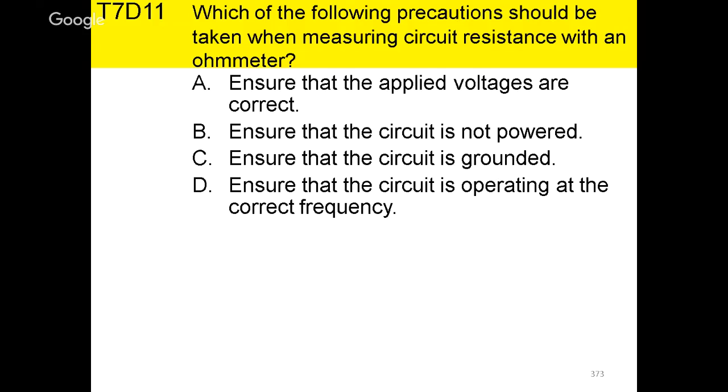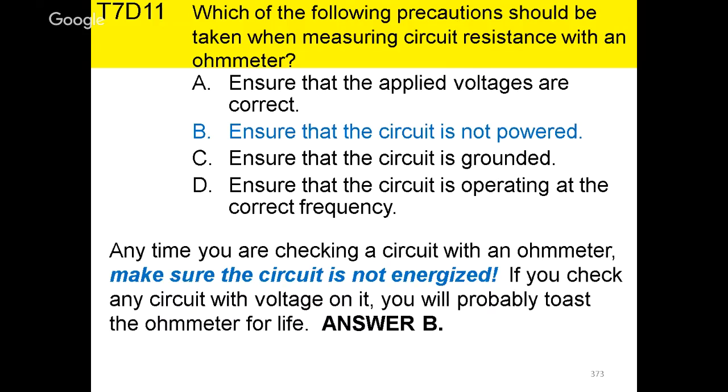So you want to make sure that the circuit is not powered before you check anything. The ohm meter will be toast if you try to check anything that is energized, and basically your meter will be no good.